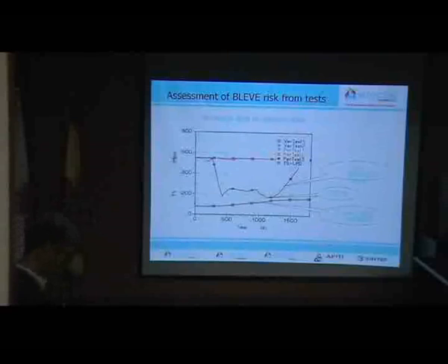Now here's a combination of the test results. Here we see all these tests, and we see the decline of the allowable stress. And again, this red one is the one with the heavy goods vehicle with 720 pallets. And here, this is also the actual stress in the last test, and here we see some critical things happening. But for the other tests, there's a big difference between the results. So the only critical situation will occur in the last test, where you really delay the suppression.